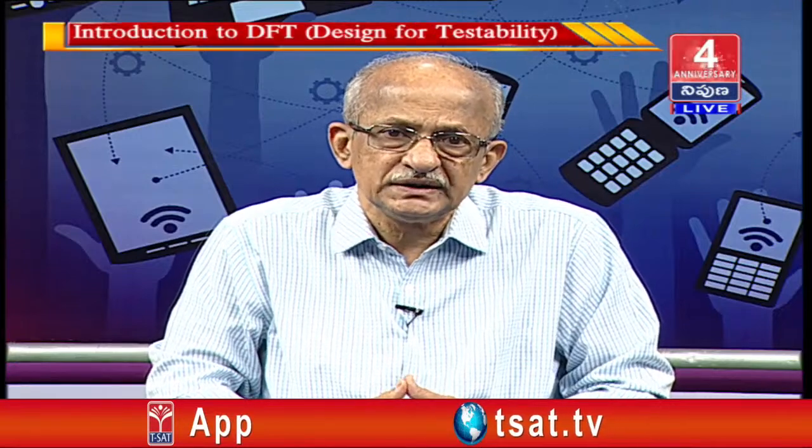When the chip is on the wafer itself, that probe will go and sit on the chip like this, and then it will apply the test patterns to the particular chip, and the response of the chip is captured back by the response analyzer, which is also a part of the ATE.